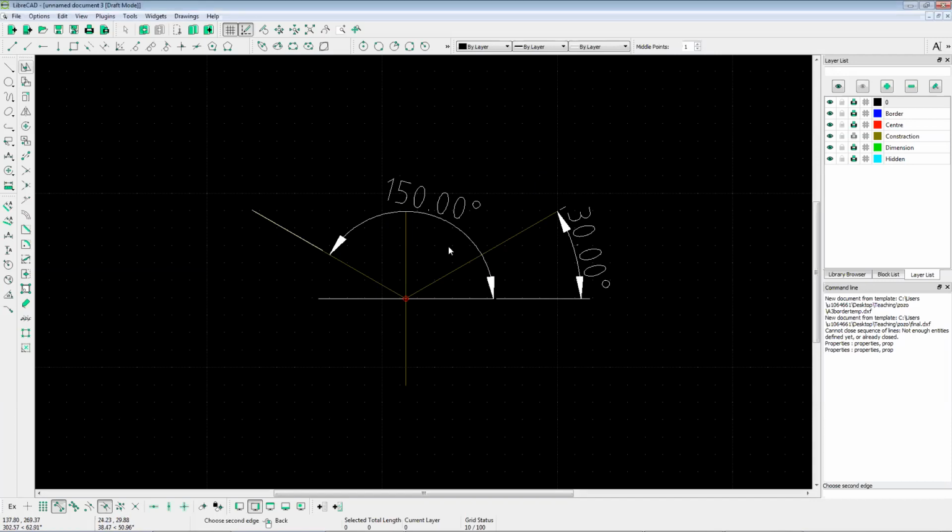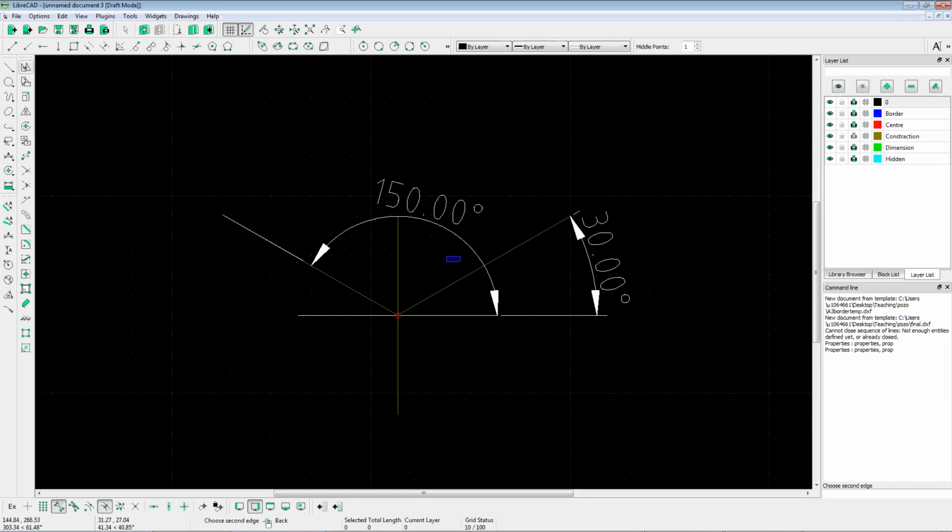So I did this sketch here to show you the principal lines, and when we are using them when doing the isometric drawing. In the isometric drawing, the vertical line will remain the same, while the horizontal line will always be inclined by a 30-degree angle. So these are the most important drawing lines, which we call the principal lines.